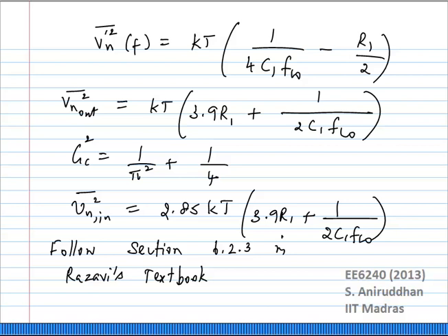For example, if you want to design an up conversion mixer, you can definitely do a decent job with a passive mixer because it has very good linearity, which is what you are interested in a transmitter. The noise figure you are really not that interested in, because your signal is already very high at the input. You are generating the signal, so you don't have to worry about the noise figure. The thing you are really interested in though is, apart from your desired signal, if you are generating other components, you really have to filter them very carefully in a transmitter.